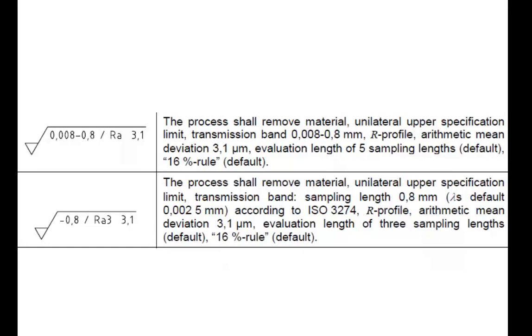But when the measured value becomes greater than 70% of the roughness value shown on the technical drawing, then the standard says to select two more regions over the surface, and make the measurement along the paths at the selected regions, and then see the measured value.